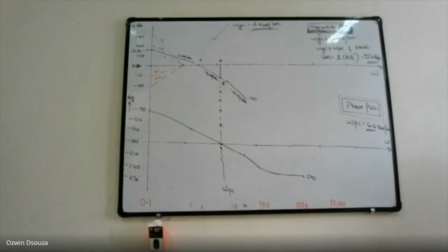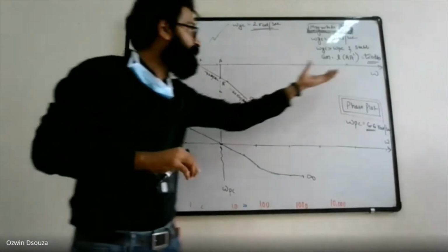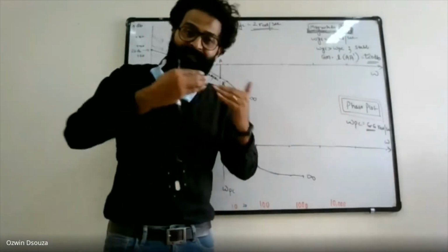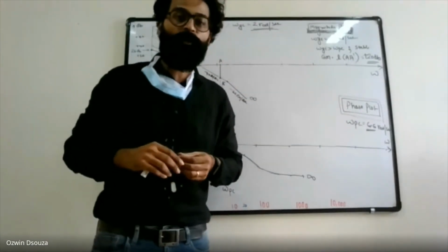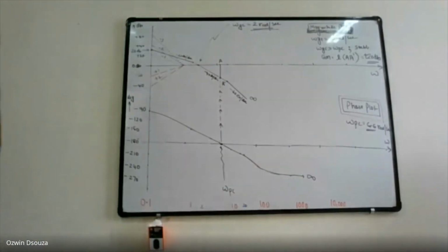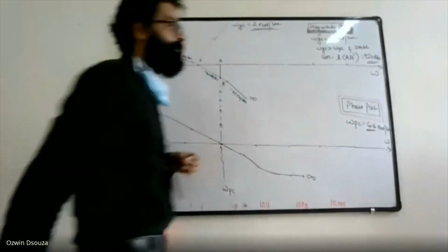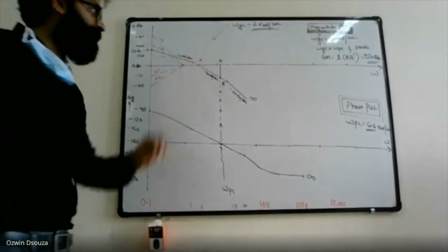This system has a provision to add an additional 20 dB of gain in order to bring the system to the verge of instability. So addition is considered positive, hence it is given as 20 decibels. Fine. So that's your gain margin.